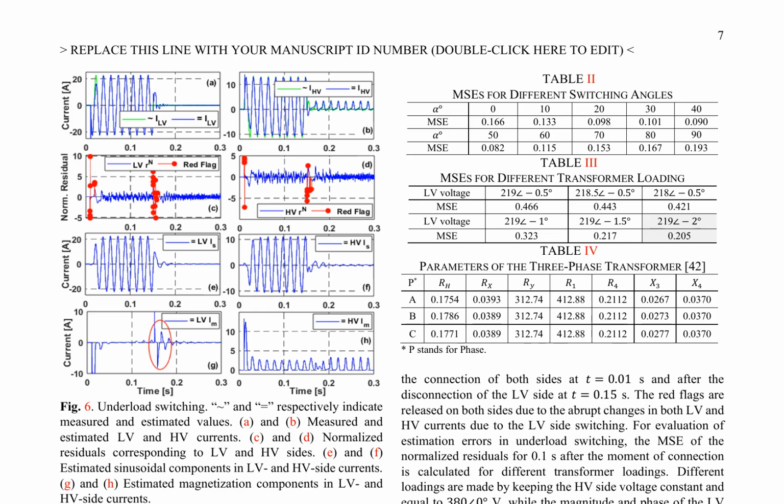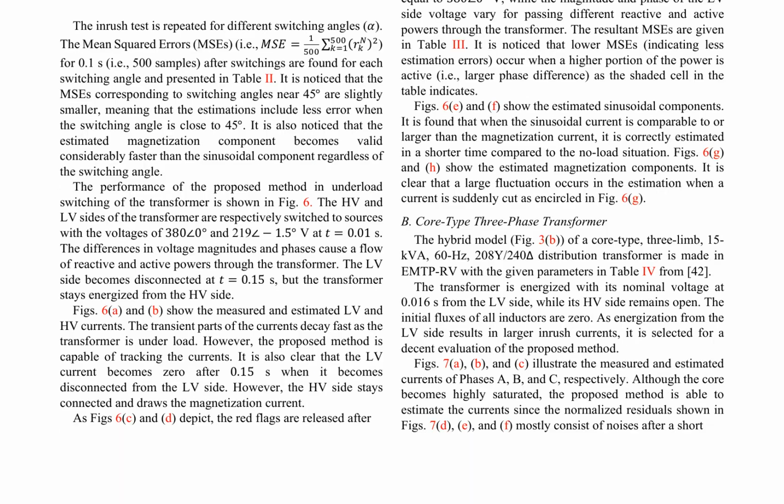The paper discusses a recursive method for developing measurement integrity verification suitable for transformer currents. It highlights the importance of ensuring the quality of current measurements in hardware in the loop, HIL, digital twins, DTs, replicating transformers. The proposed method utilizes the Adaptive Extended Kalman Filter, AEKF, to estimate parameters of measured currents and evaluates these estimations using hypothesis tests. Valid estimations are then used in the reconstruction of measurements, significantly improving the performance of DTs.